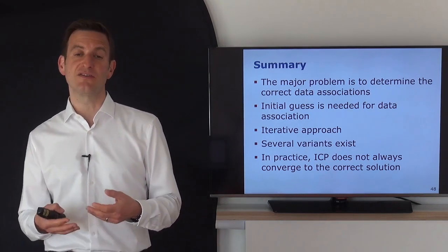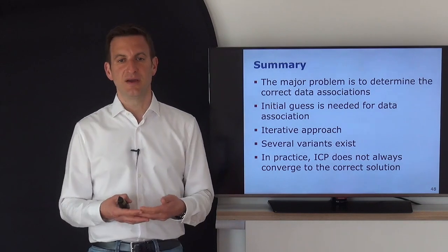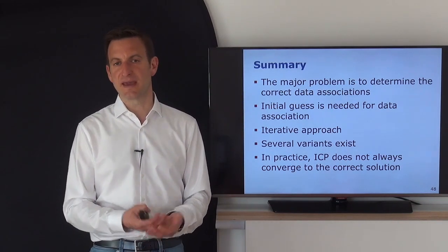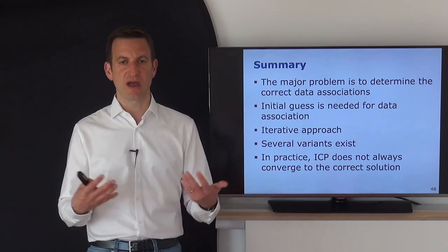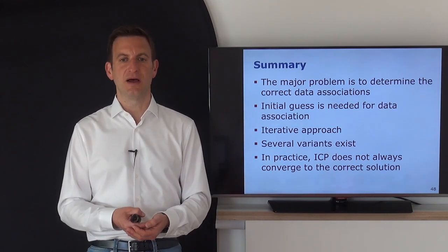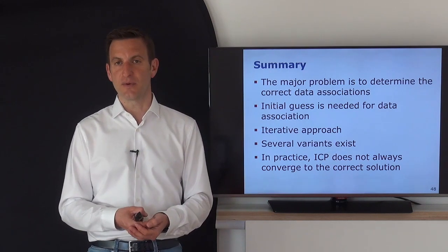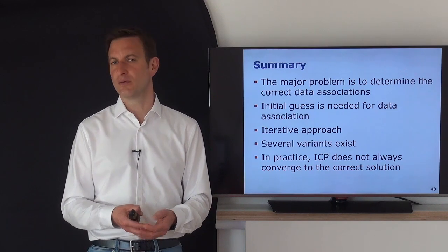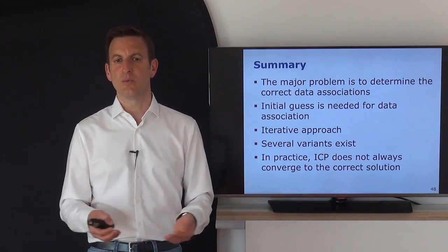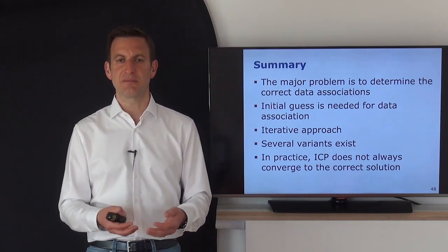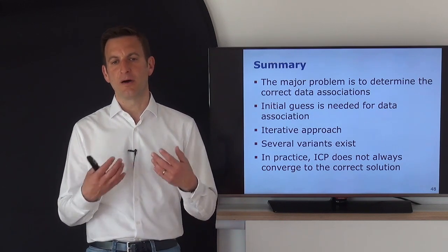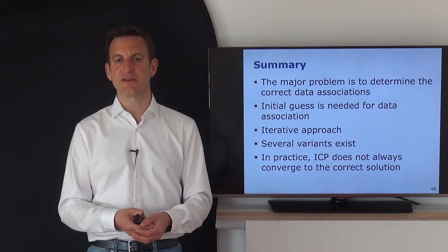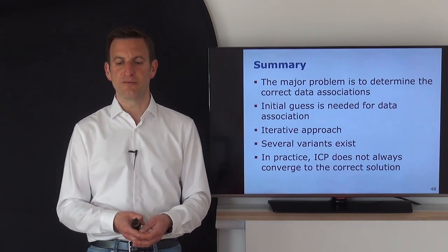In most situations, ICP works surprisingly well, but if you have to align hundreds or thousands of scans, there will be situations in which you make errors, and you need to take those errors into account in your SLAM system, for example, that you have ways for dealing with those outliers. There are different techniques that we will investigate in the remainder of the course for how we can deal with outliers. Again, one idea is RANSAC, a sampling-based approach, or optimizing not for squared errors, but using some robust minimizations or robust kernels in order to perform better here.